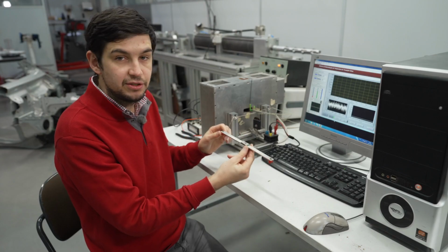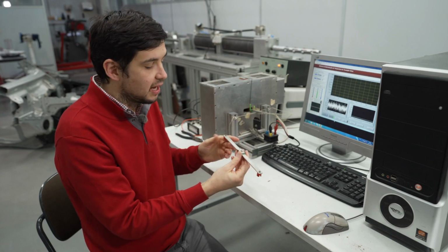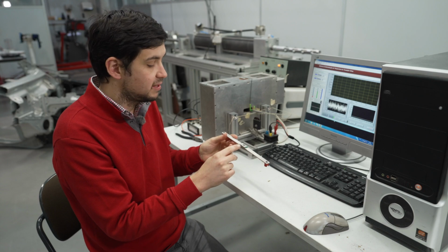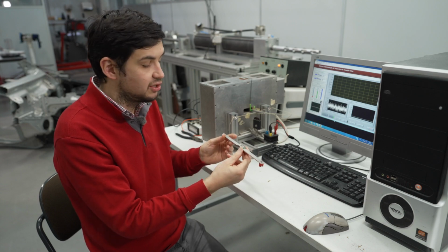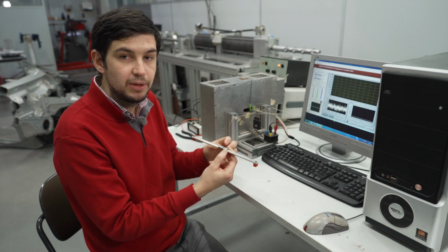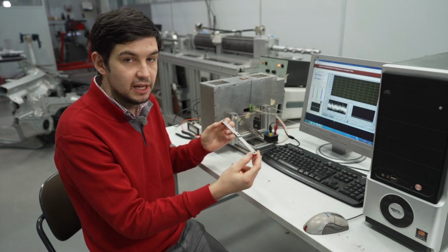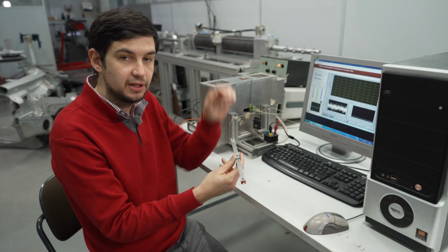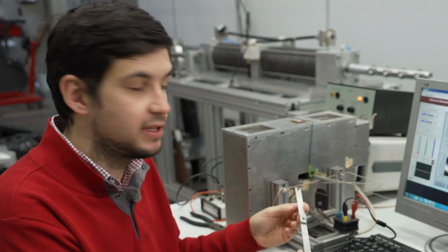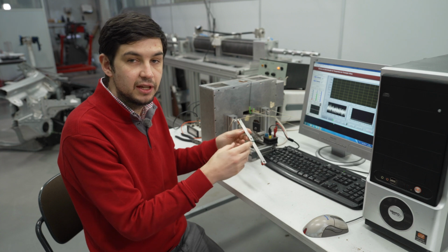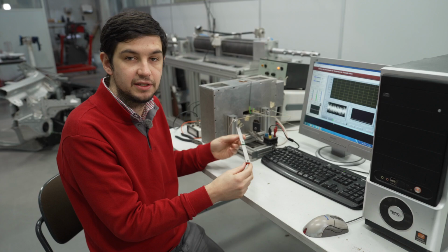To determine the glass transition temperature, what we need to do is use this oven to increase the temperature gradually until we reach a point where the specimen damping is maximum. This means that the adhesive has reached the glass transition temperature. And during this transition, it becomes very capable of absorbing these vibrational movements. And this will be reflected into a peak of damping. So we will insert the specimen within our testing machine, and we will start the software that will put the specimen in resonance, increase the temperature of the oven, and then detect the glass transition temperature.